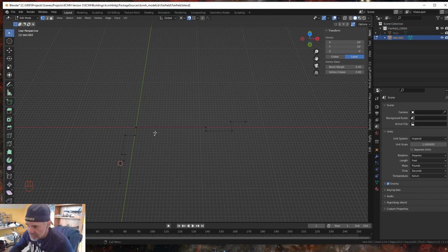I'm going to extrude this 30, so I'm going to extrude Y 30. And then when I hit enter, since I have the merge tool on, it's automatically going to split this line right here. See, now I have a vertex sitting right here. And this edge is now split. Okay, see how that works?